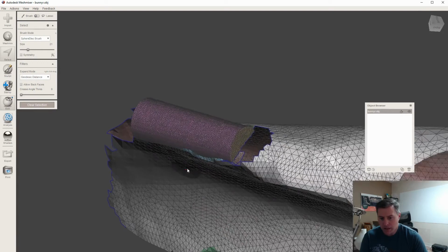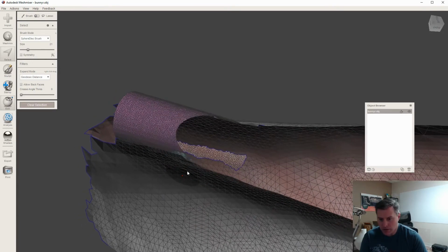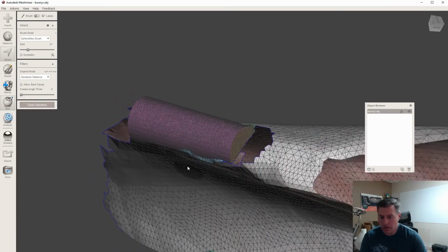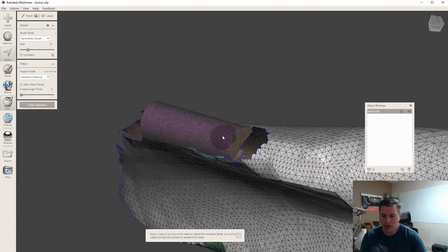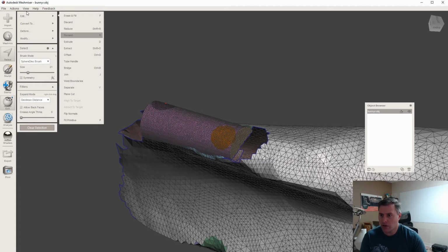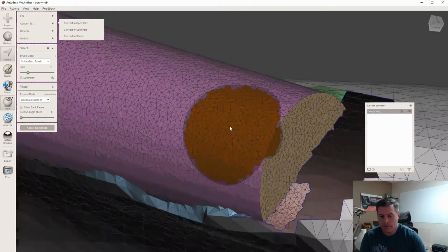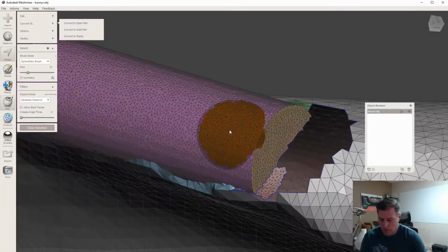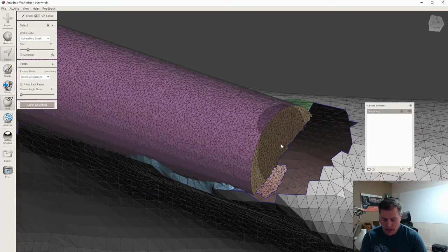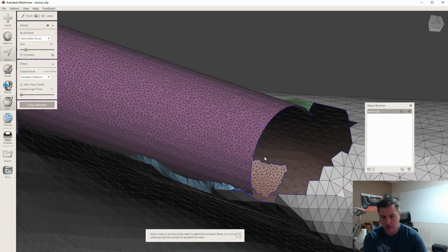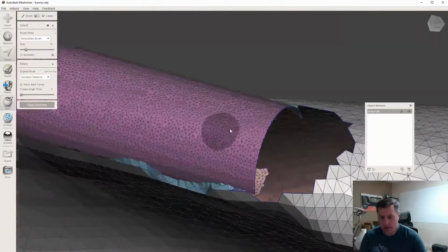And you also see that if I zoom in, I'm starting to lose all of this. This is because of a clipping distance. The way to get around that is just select a little area like this and go to View and Recenter View. And now we can zoom in all we want. Probably don't need this edge right here, so since this is actually a different color of face group, I can just double click on this. It'll select the face group and get rid of it.